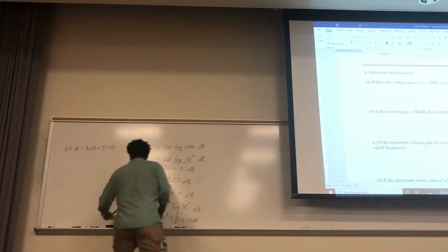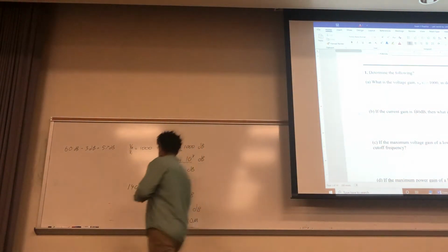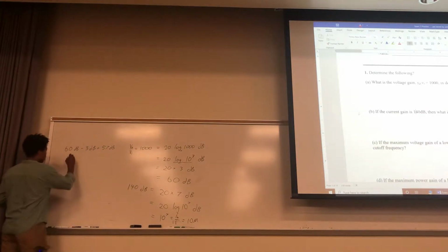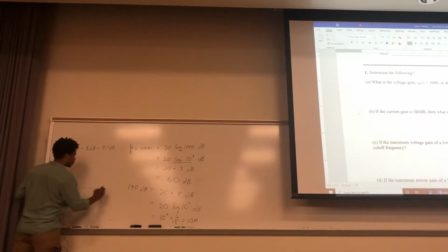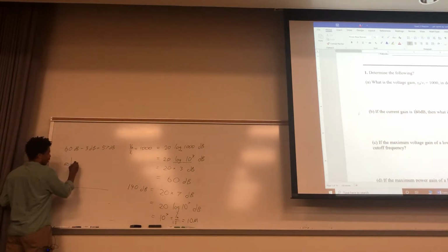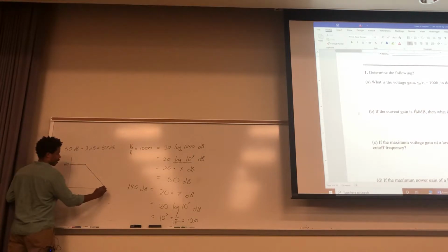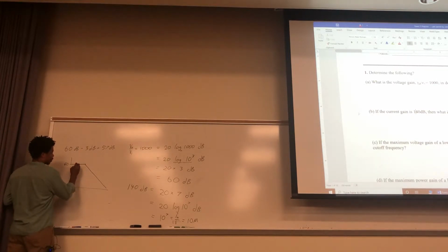This last one right here. Just to remind you guys, remember what that looks like on the semi-log plot, where here's 60 decibels, and if we do a low pass, it goes like this. We've been doing it this way, where it's a very sharp inflection at negative 20 decibels per decade, but it's really a curve, right?